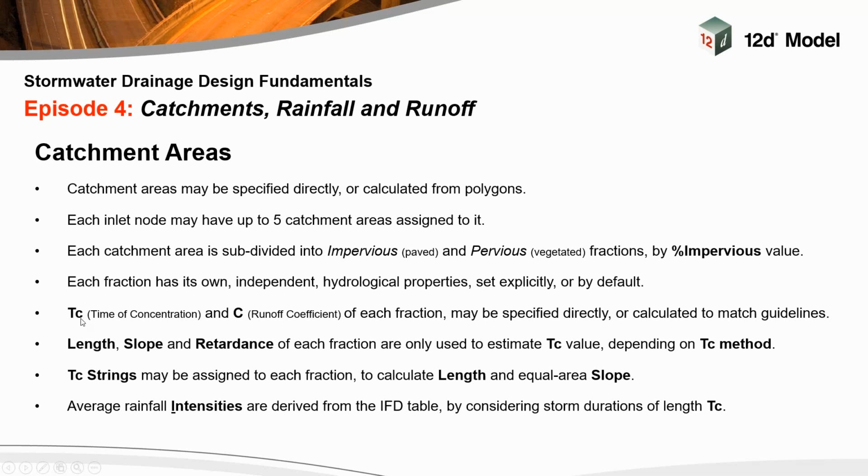That is the time it takes for the whole catchment area to contribute to the bottom of the catchment at its discharge point. Okay, and that is a critical factor, and it's also a very rubbery factor too. Our general recommendation from me would be to treat all times of concentration and all C values with suspicion at all times, and to do sensitivity analyses on them, because don't expect any high level of precision in any of these numbers. It is not a precise science, stormwater design, if it's even a science at all. It could be part art as well.